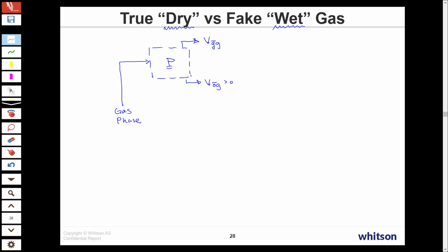And this gas here, we're going to use and label as dry gas. Now, what do we mean? We're not talking about the dry being down here. We're talking about, is it a surface dry gas? Well, it's dry. It's been dried. Why we call it dry is because we've removed surface condensate. Right? We've removed that into its own product here. So this is true surface. That surface gas is dried. Been dried, liquids have been knocked out through the separation process.